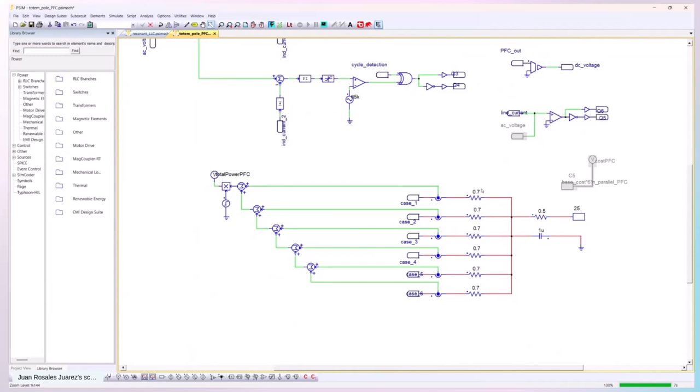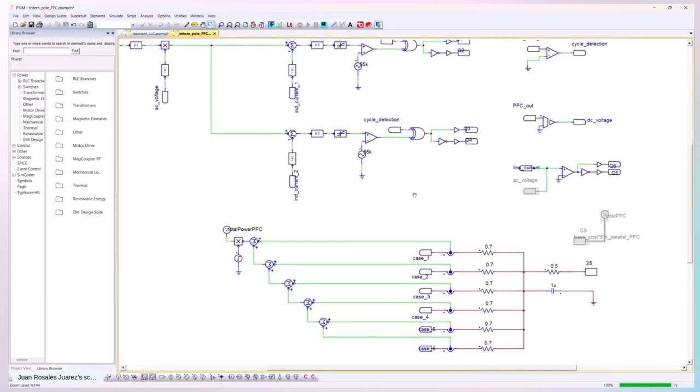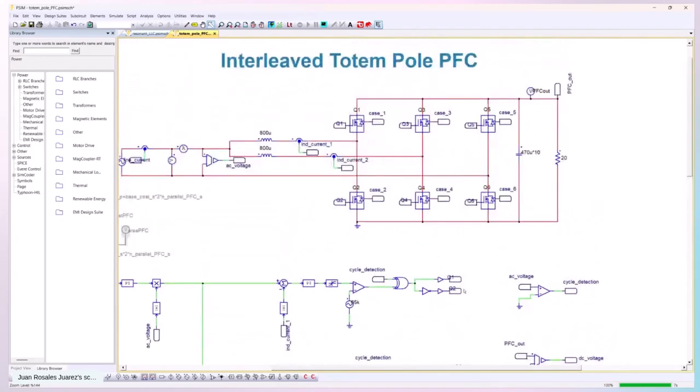So all of these transistors for now would be interfacing to the same point with a heatsink. Now, again, this part is not supposed to represent real life that accurately. Again, this is for the purposes of demonstrating this idea. So yeah, what we get is a very simple thermal circuit, and what we do is measure power as a current through this thermal network, and we calculate the sum, and then we get the total power that comes from the switches.